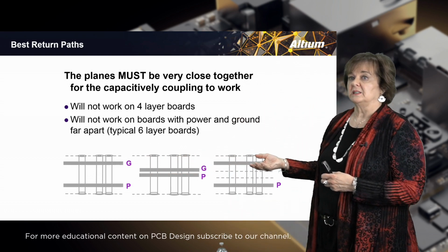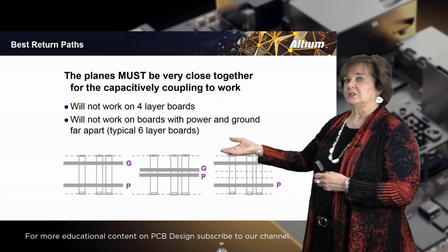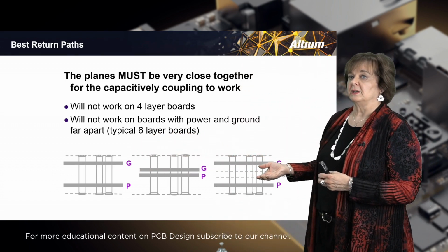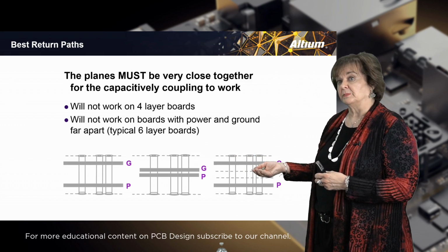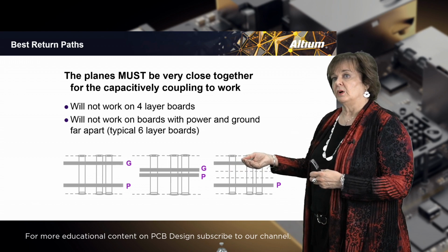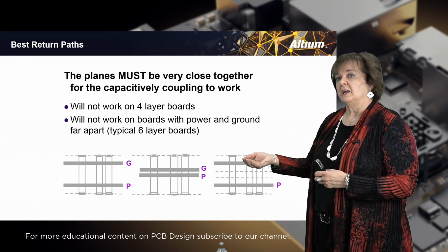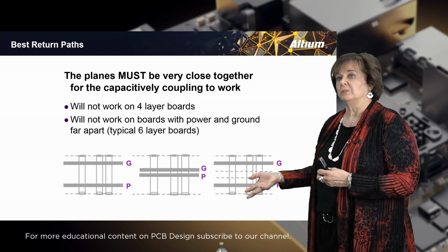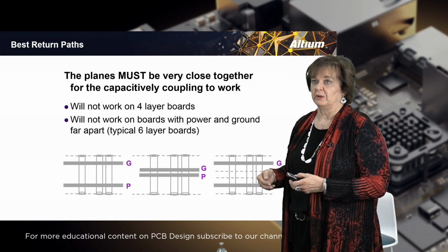This is a 6-layer stack-up, which is just taken this particular 4-layer stack-up and put 2 layers of signals in between them. And in doing so, yes, the signals could route on opposite sides of this plane, but they could not then transfer to this particular area down here because it's referencing power, it's not referencing ground.